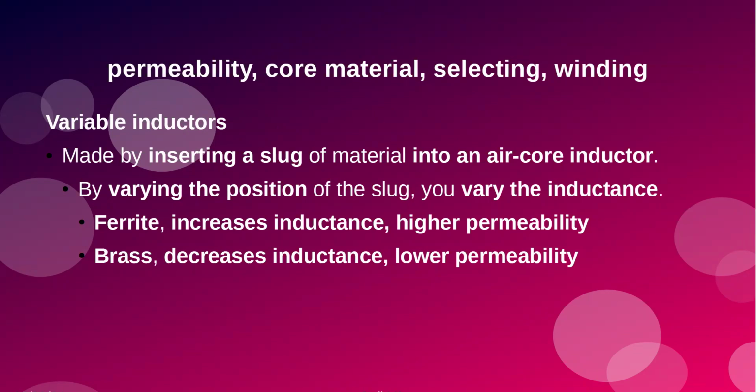You may have seen some mobile antennas on the back of a car, and has a big thing called a screwdriver, and one of them has a motor and can change the core and effectively change the inductance or loading to make it appear longer or shorter for what band it is trying to operate. And like I said before, brass decreases the inductance whereas ferrite and powdered iron increase it.